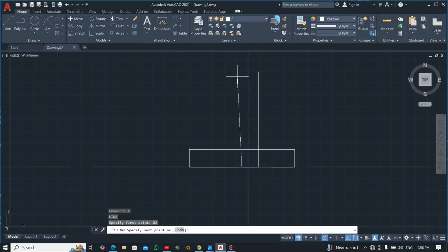Okay, then I think I made a mistake. Sorry, that's a problem. So just click on the line command, you come to the end point, you drag and then you enter 82. Okay, so now this is where the 82 is.